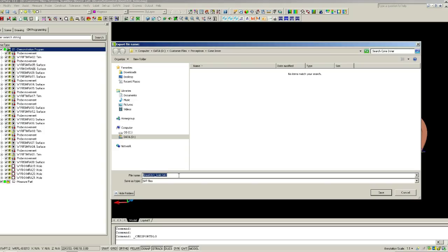So you're going to end up with extra CAD data when you go and try and load it into Checkmate for SolidWorks. This is a Mechanical Desktop bug, and there's nothing that we at Origin can do about this. So if you're going to export this SAT from the same file more than once, definitely choose a different file name. So let's go down here and say new file name or something like that. Don't use the same name that you've already exported it to, because it will not overwrite, it will append it.